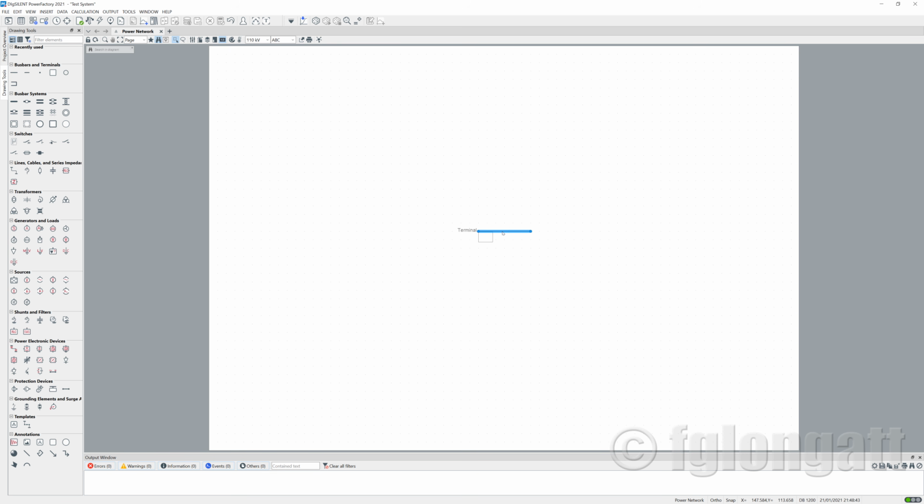In order to replicate the same structure that I have in the presentation, I will rotate this. To rotate this, I will rotate it clockwise, okay? Right now it's in this way, and because we want to have two more of this, let me copy and then paste. You can use copy and paste inside PowerFactory. Right now you can paste here and you can paste here, okay?